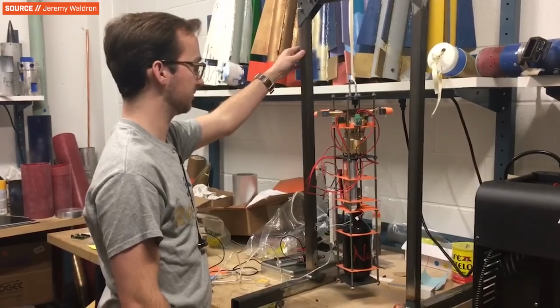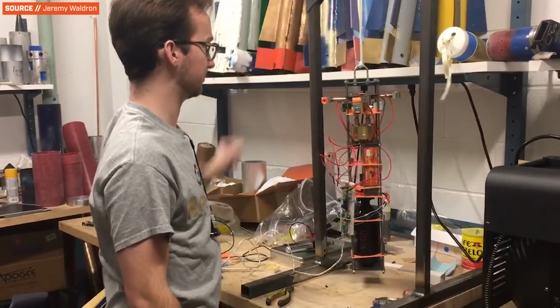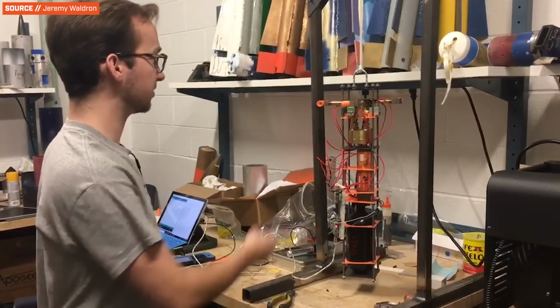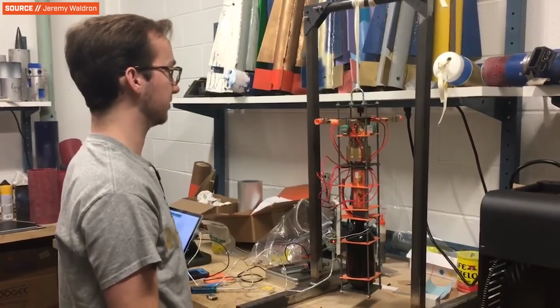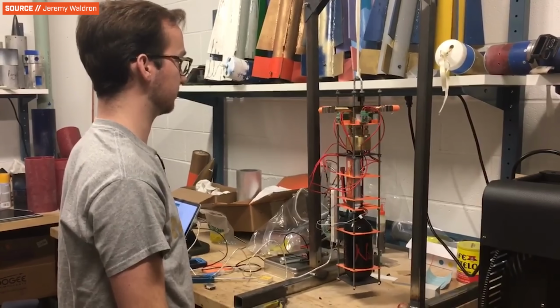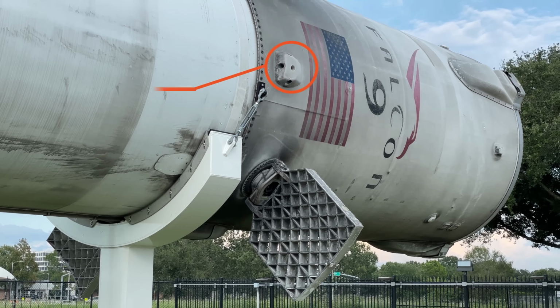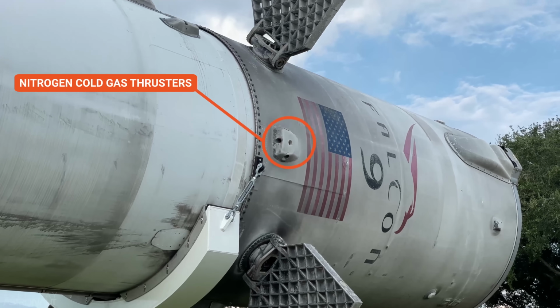And despite their low efficiency, because of their simplicity and lack of parts and weight, sometimes they're actually the best choice for really small spacecraft like smallsats or CubeSats. Because think about it, there's some things you just can't really shrink down that much more. Like a valve can only really get so small. So if you have to have 2 of those or 4 of those or whatever, that adds up in a hurry.